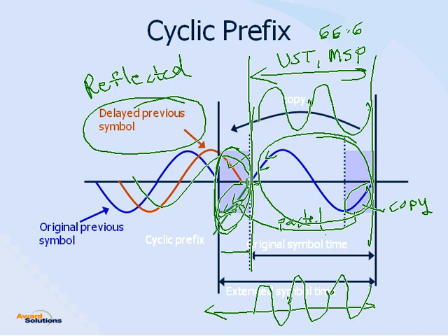So as long as we have enough length for the cyclic prefix, then we are okay. That is the solution to the inter-symbol interference problem. At the boundary between those symbols, we have to have some extra signal. In a very simple implementation, the user can just ignore the initial portion of the signal and focus on the remainder, and that should give you nice cycles of sine waves, and then we have good orthogonality during the useful symbol time.